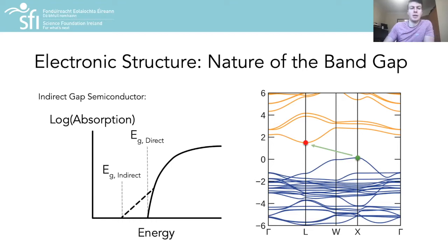Whereas for the indirect materials, you need a much thicker film to ensure that they're absorbing most of the photons coming in. So this is what silicon solar cells are based on. And why we don't want this, well, there are many reasons, but the big ones would be firstly cost. A thicker device just means it costs more to make because there's more of the material there. But also having a thinner device can help charge carrier collection and efficiency.